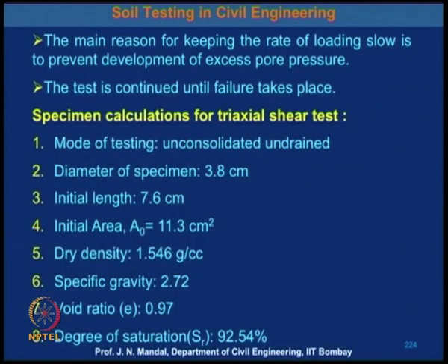Now, the main reason for keeping the rate of loading slow is to prevent the development of excess pore water pressure, and this test is continued until failure takes place. I will just show you some specimen calculation for the triaxial shear test. So, this is the specimen calculation for the triaxial shear test.